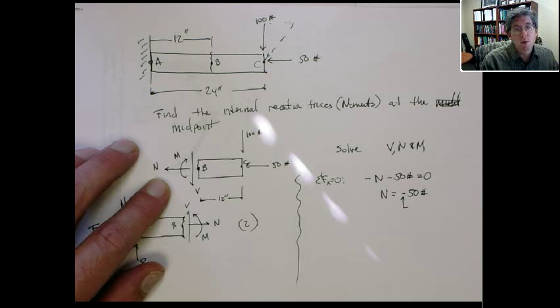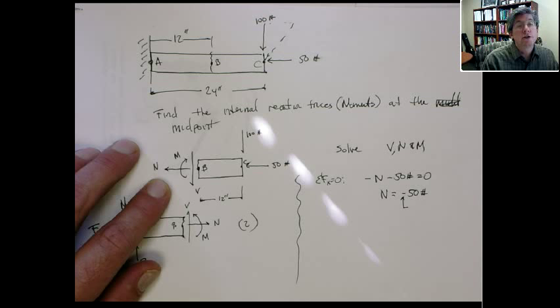If you're good, maybe more complex problems, you can figure it out by inspection. But as problems get more complicated, it's really difficult to correctly pick the orientation. Now, that being said, why waste your time doing that? So what I recommend is not trying to figure out which way the internal reaction forces should go. Just draw them on the free body diagram and then solve for them and be careful about the signs. That's all you need to do.